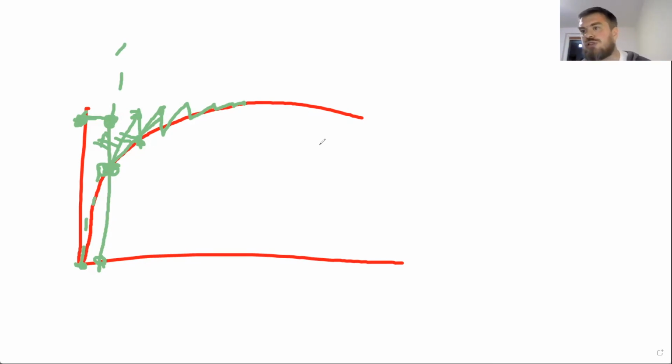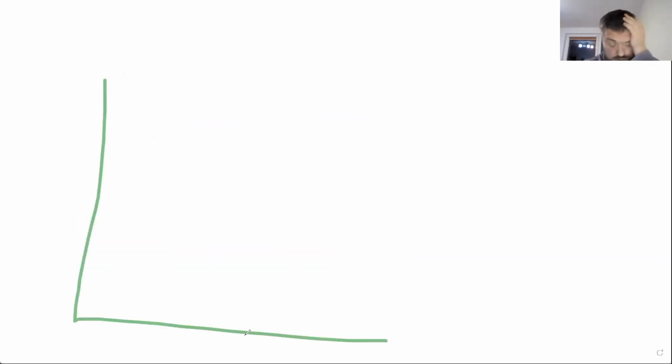And when it comes to mesh convergence, you always do it the same way. You just make a coarse mesh, calculate, smaller mesh, calculate, smaller mesh, calculate, and compare outcomes. If the outcomes are similar, at some point, of course, so imagine that you have a mesh size, and this is a lot of elements, and this is the outcome, whatever you measure, like stress in a place of interest, deformation in a place of interest, something like this, right?